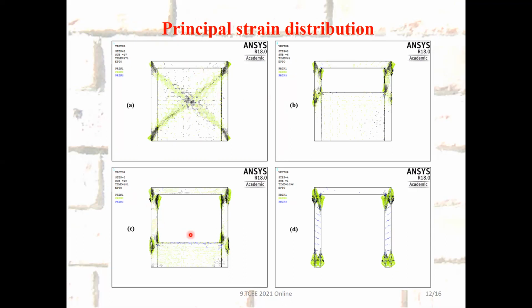When the infill ratio decreases, the short column effect appears. The black points at both upper corners of the masonry wall, the upper corners of the frame, show the location of the plastic hinges here. And due to the short column effect, in the confined masonry walls having 2/3 and 1/3 infill ratio, failure of the system occurs at the interaction point of the frame and the masonry wall system.